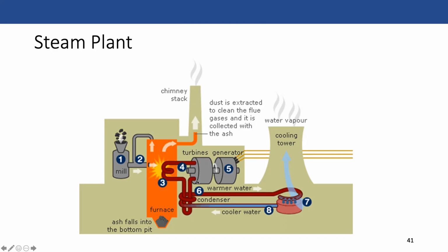Well, the water that you want going through the turbine, you want it to be really pure, right? If you have any impurities going into the turbine, eventually that's going to build up and you need more maintenance and more cleaning. And so what they've done here is to create a separate loop where now you can take water that cools down the stuff coming out of the turbine and gets sent back through.